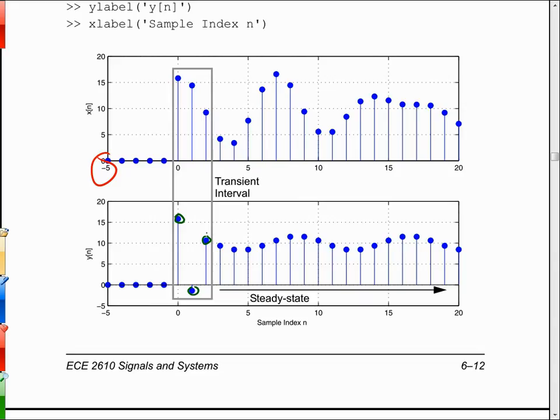It was annihilated, right? It was gone. So looking at that steady state output on that bottom plot, what does that look like we have? Just visualizing, what do you see? It's a single sinusoid, but we also have a DC present, and what did the DC do? It just raised the signal up onto an offset of 10. So the impact of the DC is to just make the signal be riding on a bias or an offset of 10, but then it looks like just a single sinusoid is the only time-varying portion.